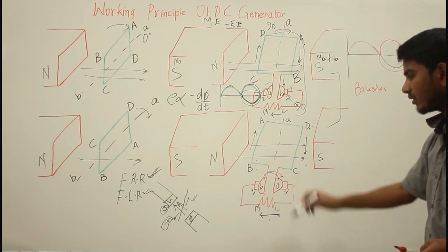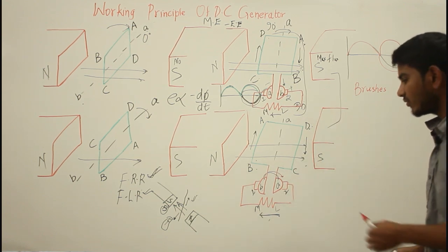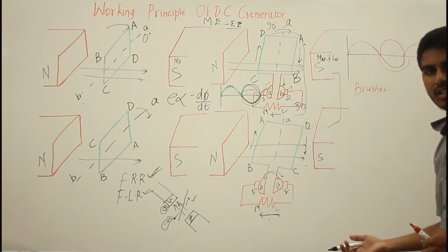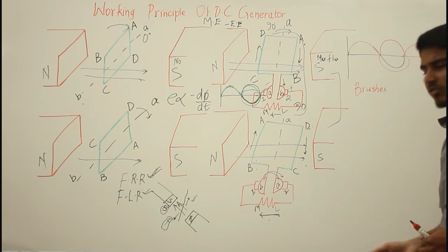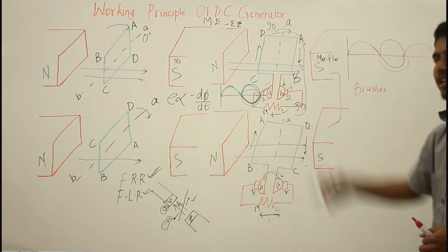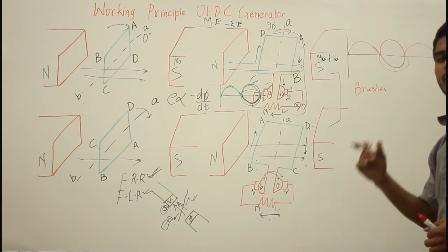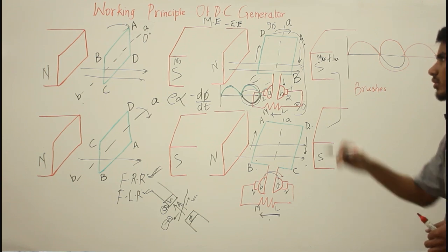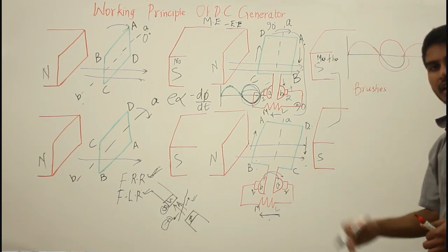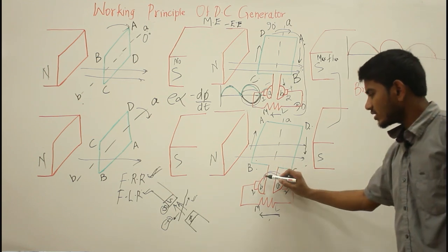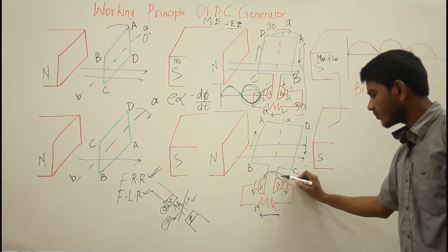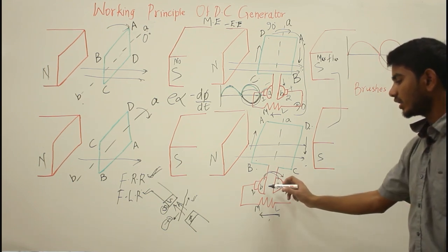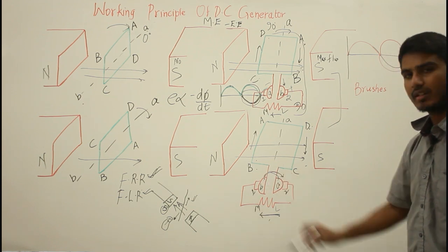Therefore we are mainly preferring the AC generator where we do not have the commutators, because we do not need to rectify the induced EMF, that is the time varying induced EMF in the armature. As no commutators are required in an AC generator, we prefer the AC generator nowadays, even though we need the DC output. The AC power can be rectified to DC, and mostly nowadays DC generators are not being used because of the sparking problems occurring in the brushes and the commutator segments.